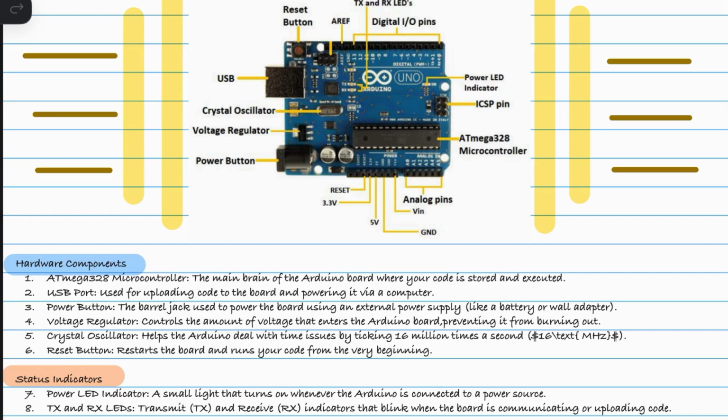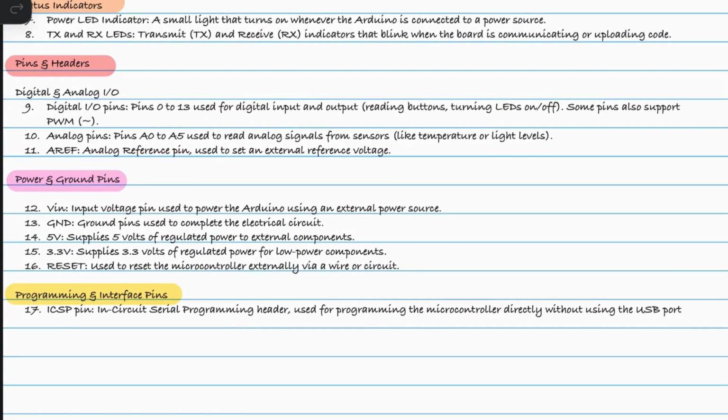The microcontroller's internal ADC, which stands for analog to digital converter, turns a smooth voltage curve into a digitalized number between 0 to 1023. All right, and then we have AREF pin. So this stands for analog reference. So if you are reading a highly sensitive sensor that maxes out at exactly 3.3 volts instead of 5, you can supply 3.3 into this pin. So this recalibrates the ADC's resolution scale, making your sensor reading much more precise.